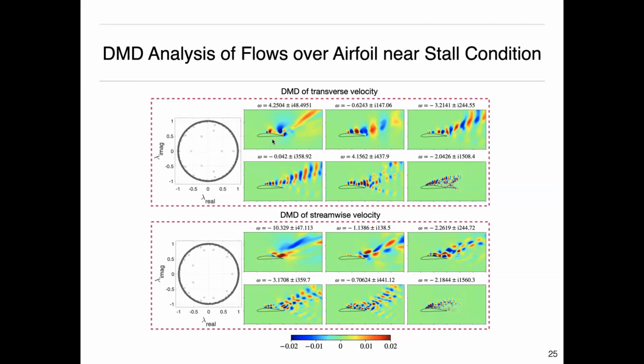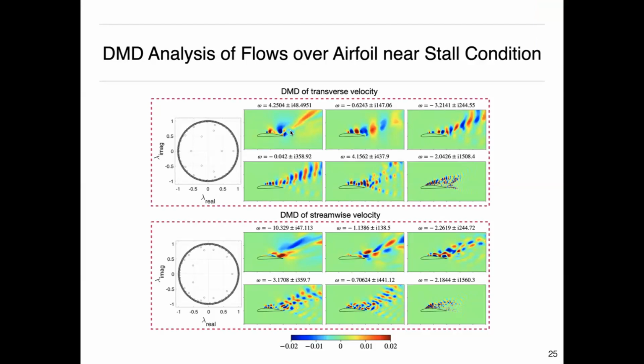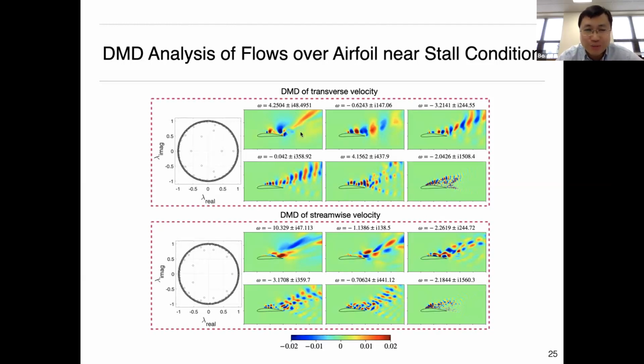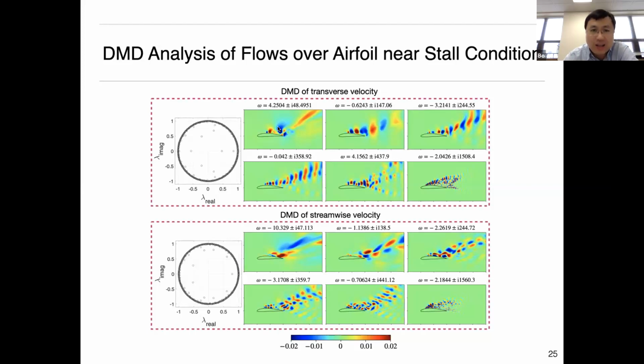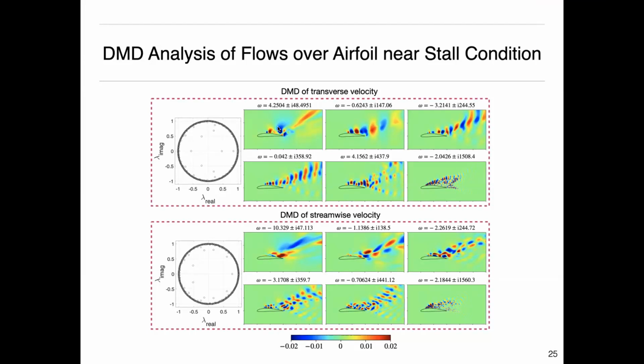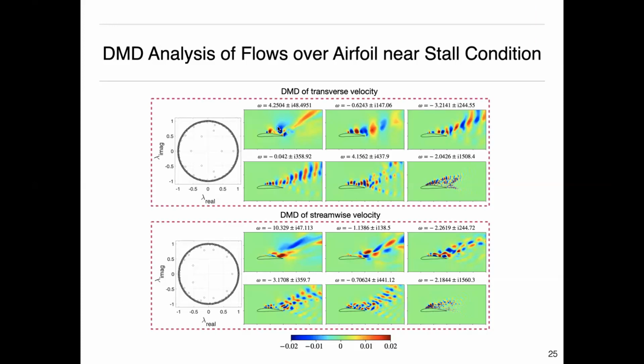So is the first mode different? That's what you're saying? Oh, you mean between the POD and DMD, right? Yeah. Between POD and DMD, the first mode is also— oh, for POD you rank the mode by the mode energy. Yes. But if you check the dominant mode, it looks different from what I show here for the DMD mode. For DMD modes, they are actually classified by the growth rate and the oscillating frequency. So actually, it looks a little bit different. So here you rank them in terms of the complex eigenvalues, right? Yeah. Exactly. But they look similar to me. Yeah, the spatial mode looks similar, but the POD cannot give you the frequency information and the growth rate information. I see. Okay, thank you.